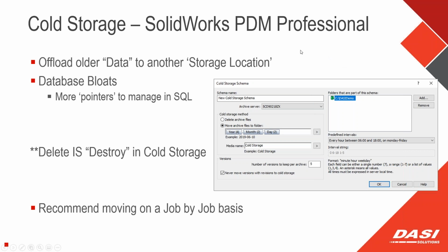Now, when you're in the cold storage location, delete there is a destroy. You have a delete operation inside of the PDM vault view, but there's a secondary operation to physically clear the recycle bin to do the destroy. When you're working in any cold storage, any type of delete, there's no recovery from that. So be aware of that. Once again, important thing to know there.